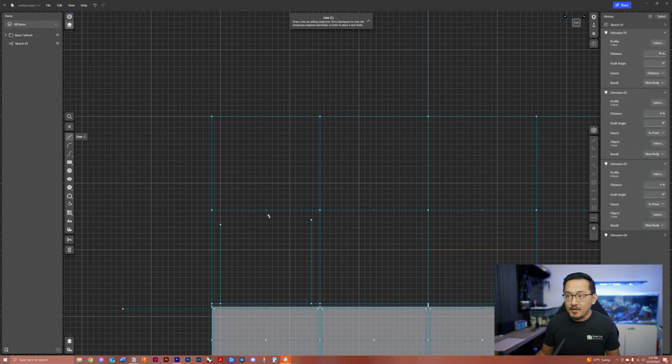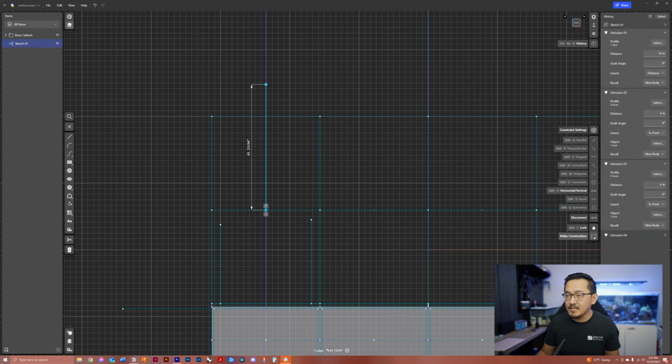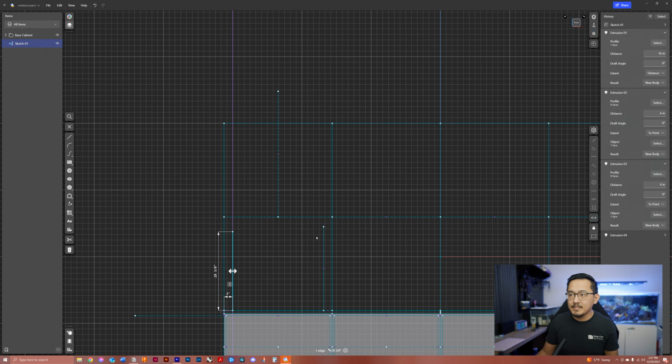So to create the arch section, I want to establish a midpoint or a midline that's going to allow me to do some symmetrical drawings. So I'm going to make that as a construction guideline. Now with these 2 lines here, you notice they're not the same height. They don't really have any connections to each other. I want to give them that connection. I want these 2 lines to move up and down together. So I'm going to use the symmetry constraint to do that.